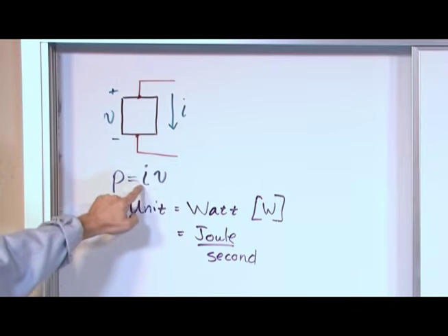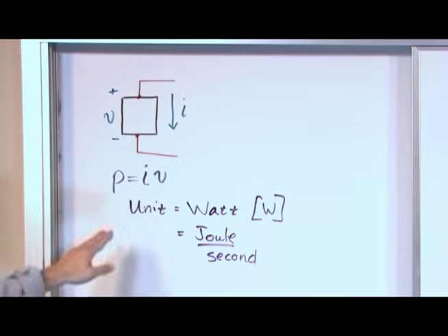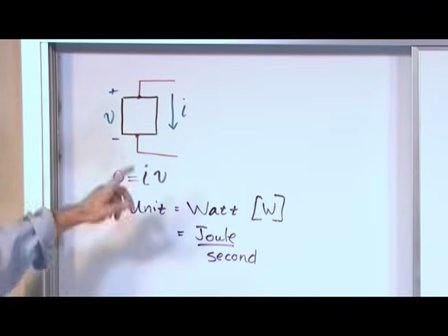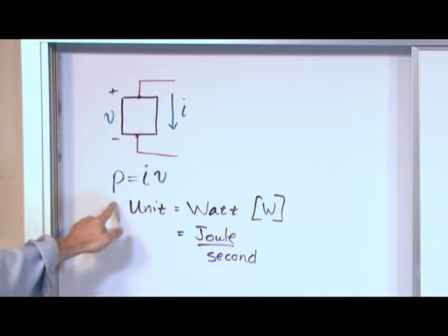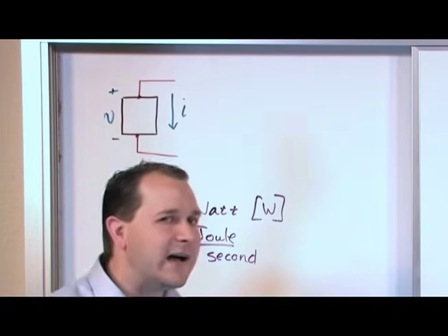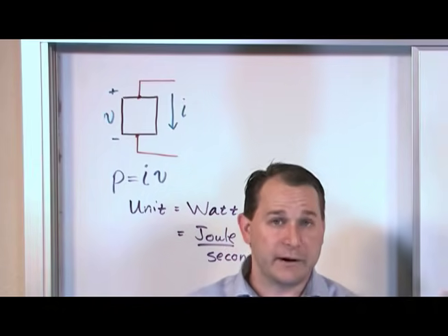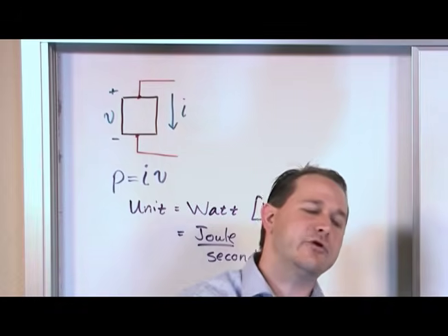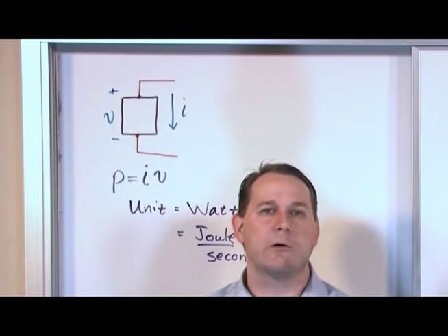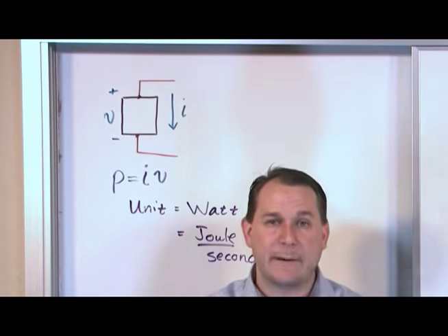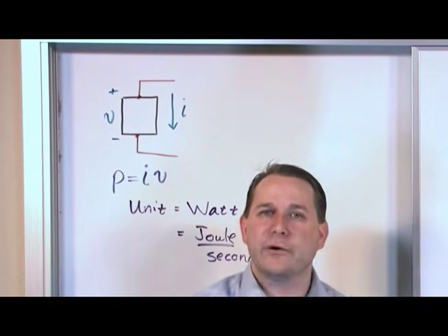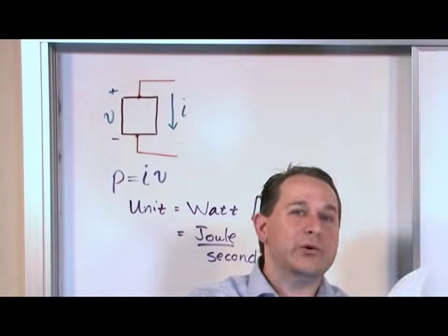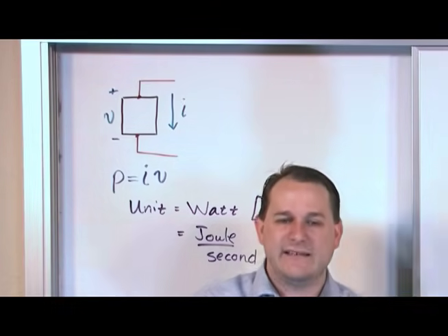See, in front of the I, there's a positive here. And so when you calculate I, if it's 5 amps, times V, which is 10 volts or whatever, then you're going to get a positive number for the power. And when you get a positive number for the power, this is the punchline, it means that that circuit element is absorbing that power. Think about your resistors. It's absorbing that power. They're getting hot. Think about your light bulbs. It's absorbing that power. Of course, it re-radiates that power as heat and light, but it's taking that power in from your source.